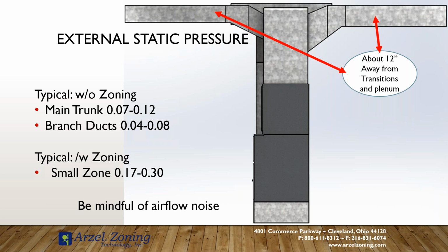So if we're looking for a 0.1, we actually see that on a 6-inch duct that comes out to 500 feet per minute, I believe. So 0.1 at 100 CFM on a 6-inch pipe, I want to say came out to about 500 feet per minute when we follow that through on our duct slide chart, which is within that range that we're given according to Manual D. So it's a nice simple chart to follow. We can use that with our ductulator to really calculate things out fast and easily and see what we're designed for.